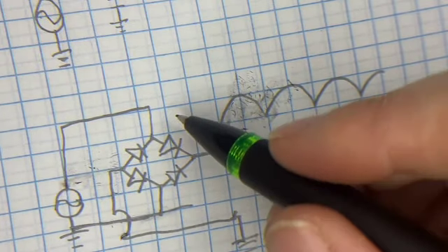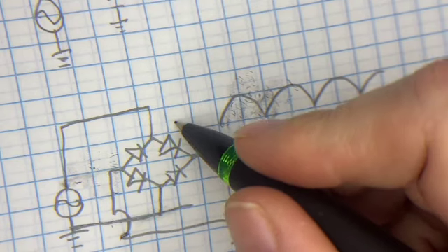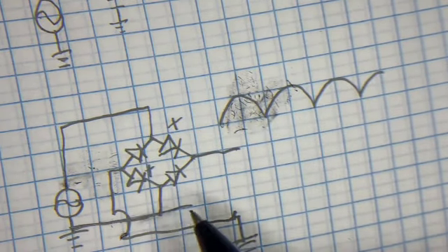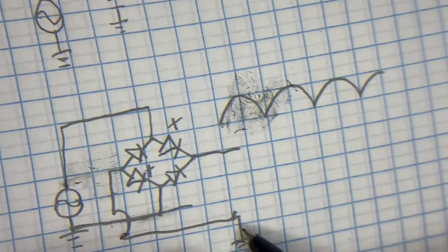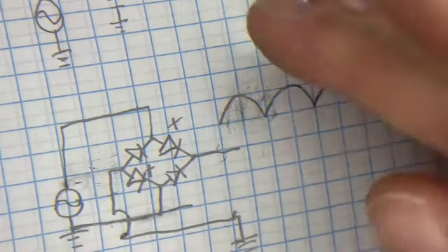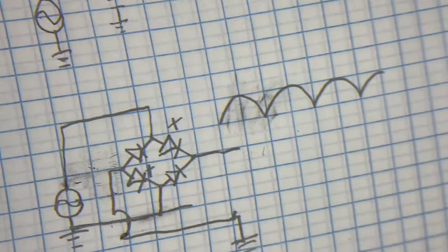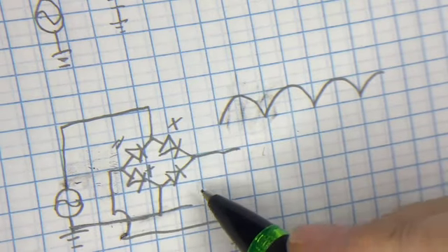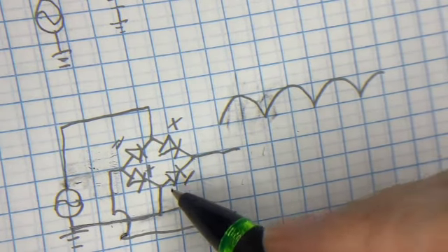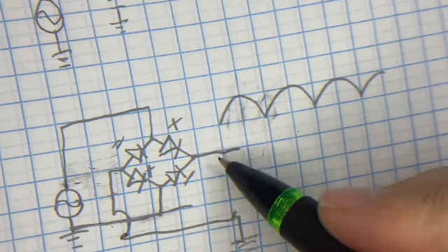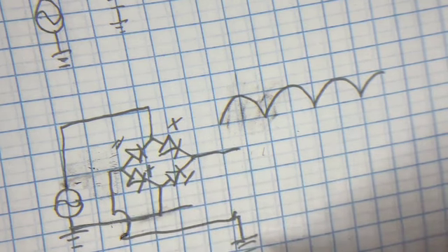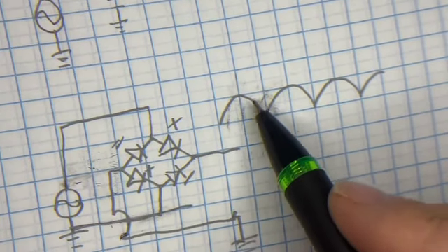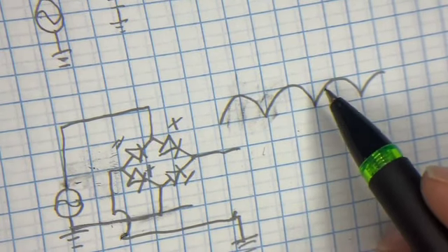So positive half of the cycle, this diode here and this diode here are active, allowing current to flow through. The negative going to the ground, positive going out to the signal. Then during the negative side cycle, this diode here becomes active and this diode becomes active. So the positive voltage comes out this side and the negative voltage comes out this side. And you get this. Now again, look at the size of this ripple and it's just too big.